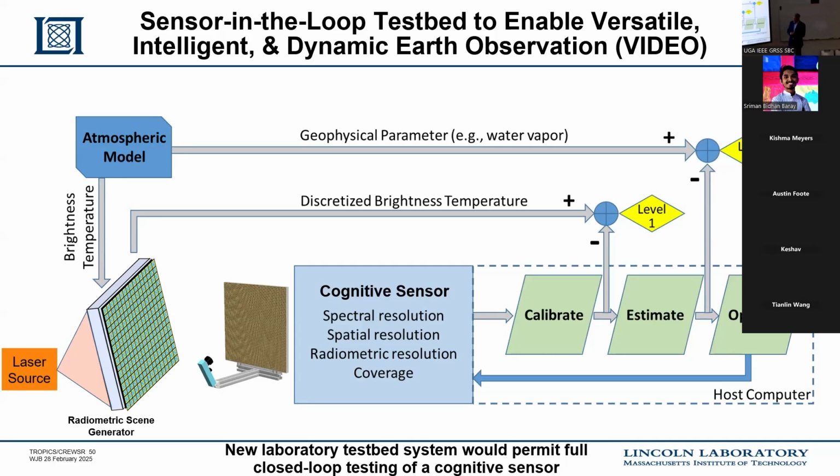The cool thing about this is the calibration target that we're using is a laser-driven projector. What's going on here is we have a metamaterial absorber, we heard about that in the last talk, a high emissivity surface that's thermally excited on the backside by a laser. It's actually 4 lasers that are projecting on that.